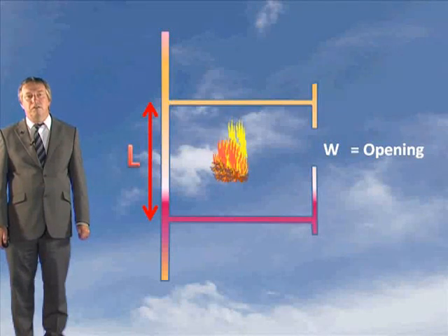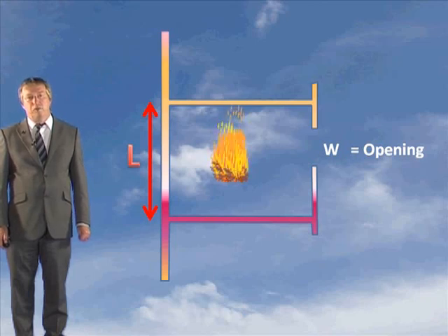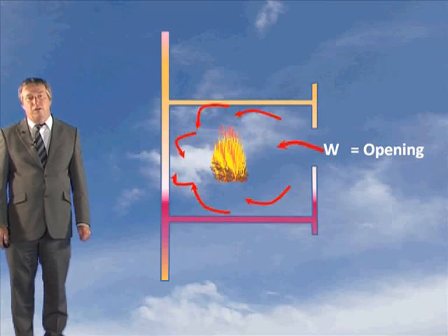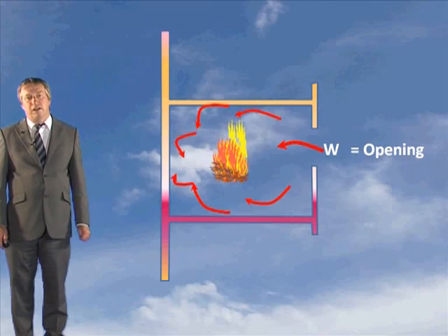In this case, rooms are considered to be small and therefore appropriate for this value of CE when the maximum room dimension is less than or equal to 5 times the diameter of the design fire size. And it must be said that air is only allowed to enter from one direction. If it comes in from 2 directions, then you're unlikely to get the fire-induced winds. Let's now do some examples looking at the simple plume near-field model.